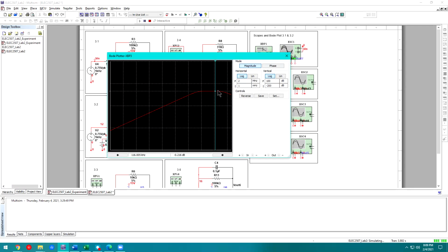So any points between, let's say, 10 millihertz and, I don't know, 1 kilohertz. Any of those points can be taken. As long as you take 2 of them and do y2 minus y1 over x2 minus x1, just rise over run as you did in grade 9, you should be able to find the slope for that line.